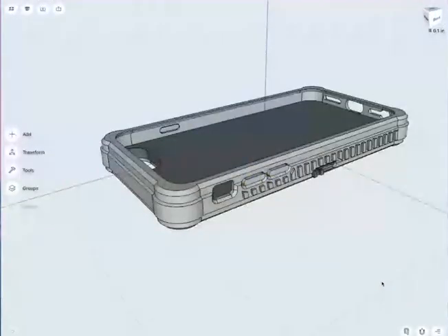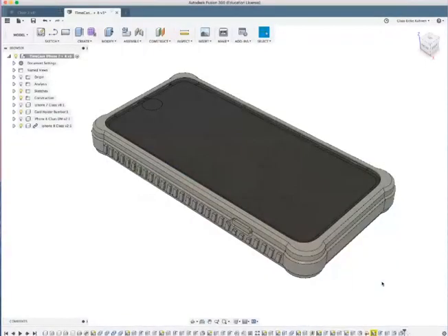If I go quickly to Shaper 3D, which gives us the ability of direct modeling, we don't have that type of feature-based approach to go backwards or forward. But what we have in Shaper 3D via direct modeling is that we can manipulate the whole design whenever and wherever we want, without having to be very careful about how we actually constructed this design. So to explain this again, let me go back to the Fusion file.